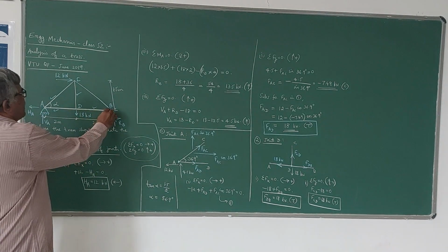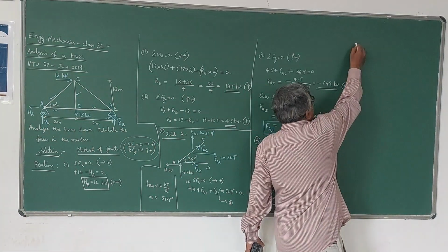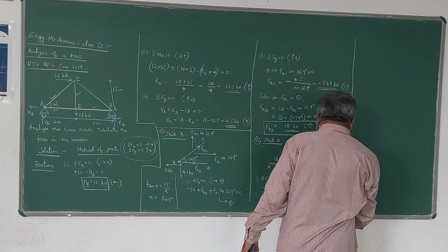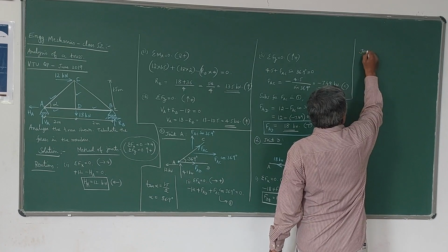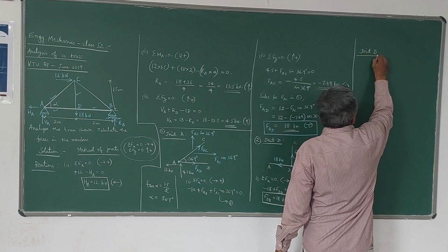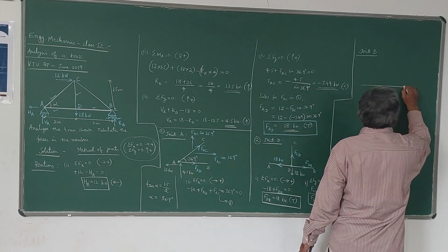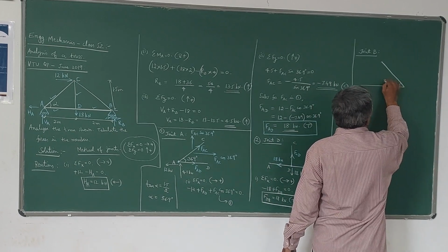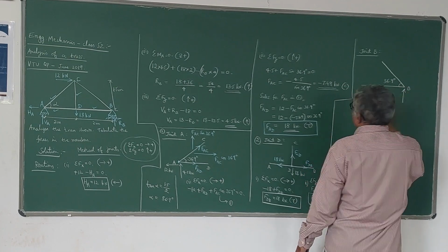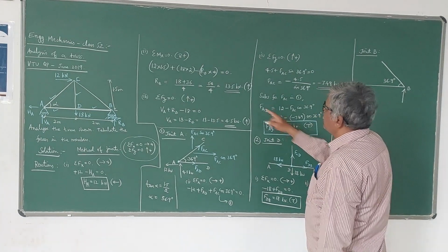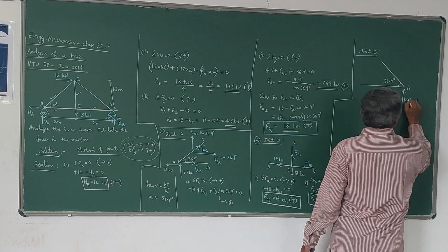Now, the last thing we need to find is the force in the member BC. For that we consider the joint B now. Either joint C or joint B can be considered. Anyway, joint B I will consider because only 2 members are meeting at joint B and a reaction will be there at B. Now let me write, this angle is also alpha, 36.9 degree. This is B. This is vertical reaction RB. So RB is 13.5 kilonewton that we have to take.